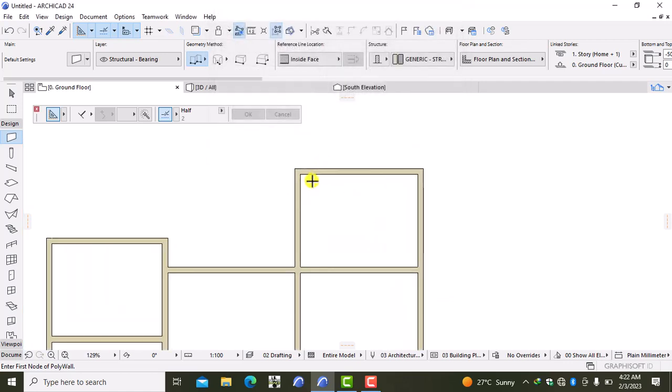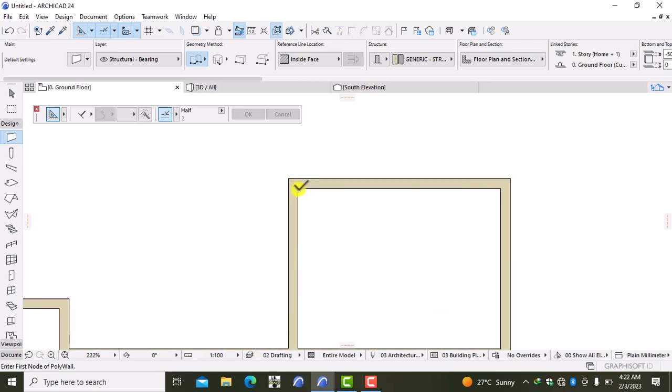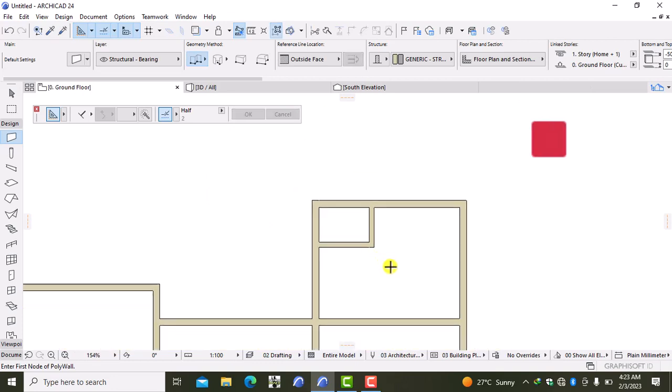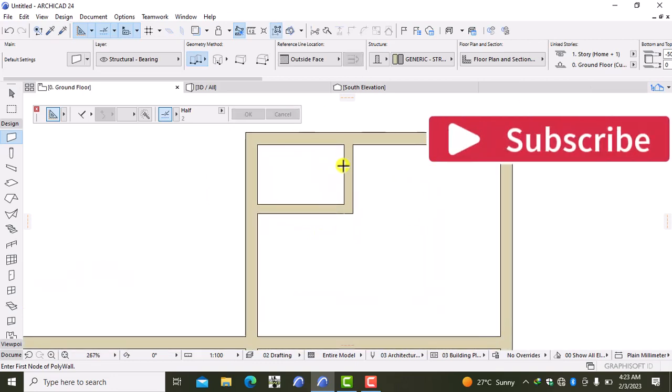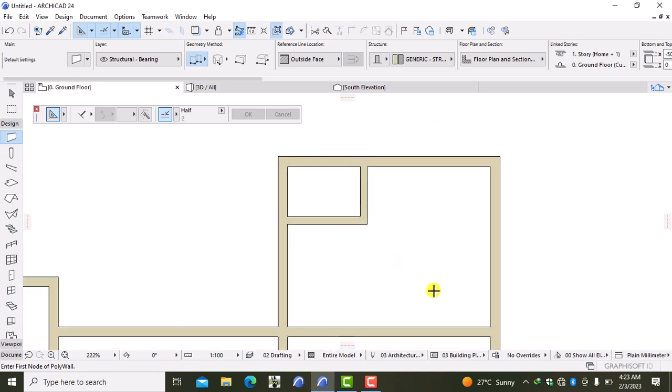I want to go ahead and create a WC over here. This is a DSQ. It can be used by the servant quarter, and I'm going to do a wall from a distance of 1500. This time I'm going to use the side of the base, and I'm dragging it to a distance of 1000. When I use a wall of 115 thickness, I'm able to maximize the space of this particular DSQ, unlike if I had used a wall of 200 millimeters thickness, which would have occupied more space.